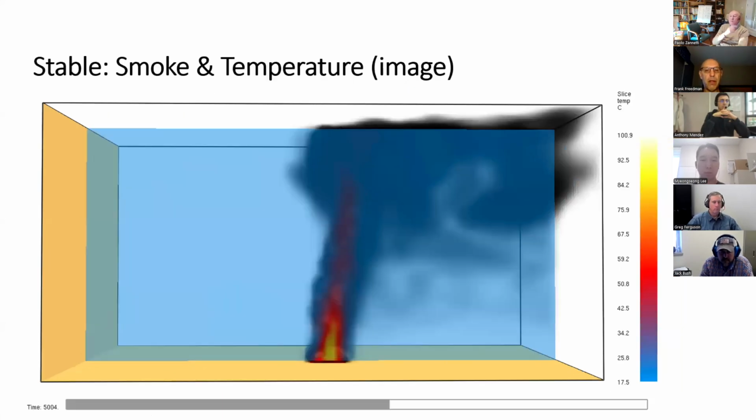Okay, so let's compare that to the stable case, and we'll see some very different characterization. Now, in neutral stability, the atmosphere doesn't have any effect on the buoyancy itself because there's no atmospheric stability. In stable conditions, the air temperature is isothermal in this example, which produces an inhibition of vertical motion due to the atmospheric stability that the fire is rising into. So you'll see that causes the flow behavior within the fire and the plume motion to be different.